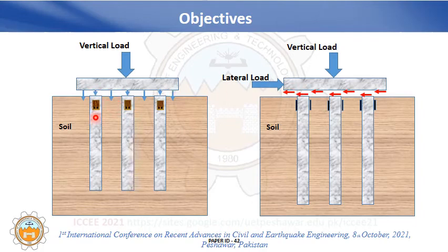We will install strain gauges on the pile using a special configuration of Wheatstone bridge to find the vertical contribution of a pile and the lateral contribution of a pile. Then by subtracting the pile contribution from the total load applied, we can find the contribution of the raft.